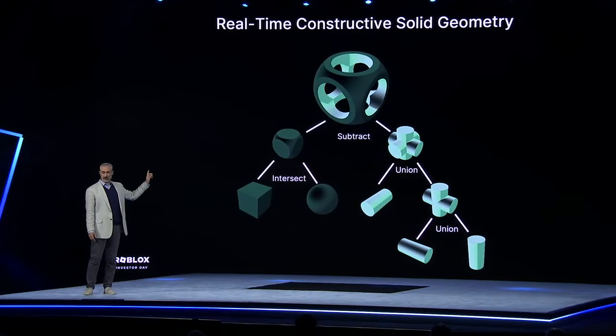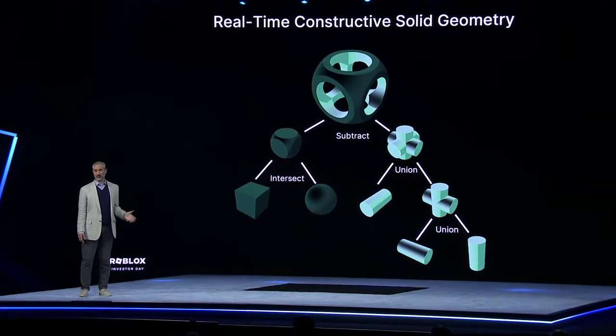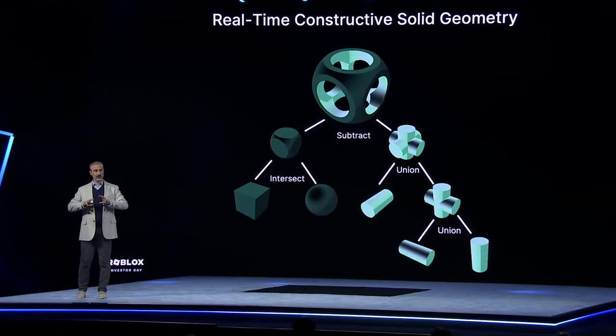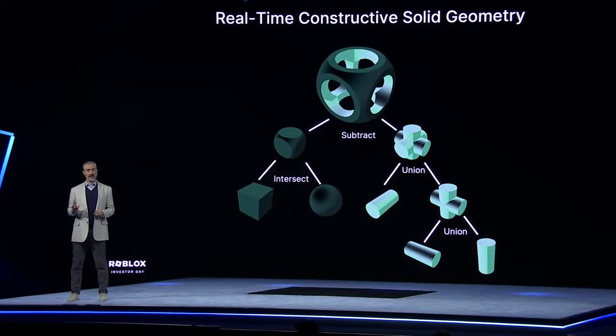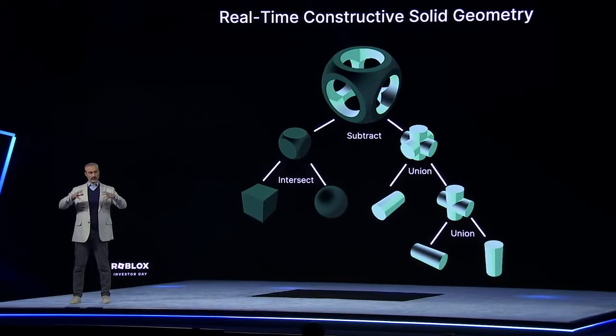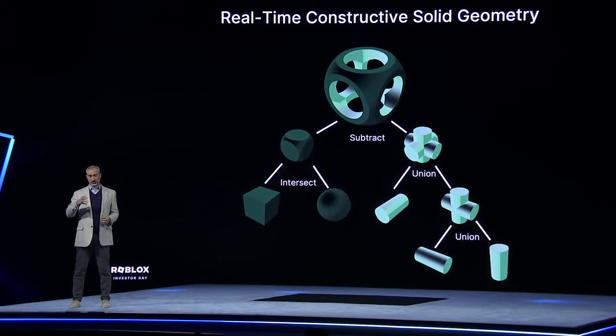And the idea is, this is how, in the real world, mechanical engineers and industrial designers make real machinable parts in their CAD systems. So you take shape primitives like spheres and cones and cylinders, and in sort of a virtual machining way, you can subtract parts from them, you can slice off pieces. And you always end up with something that's real, physically simulatable, and physically buildable. It also, for many people, because it corresponds to real-world building and not a computer graphics concept, is a fairly intuitive way to build compared to mesh editing.